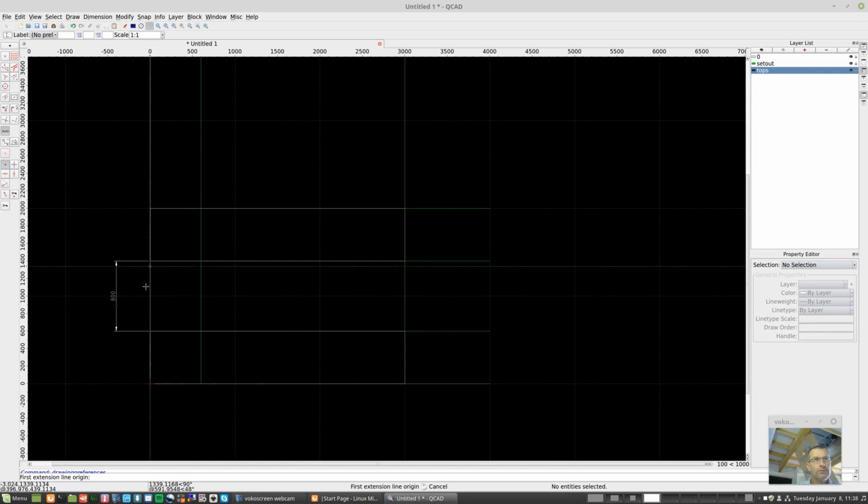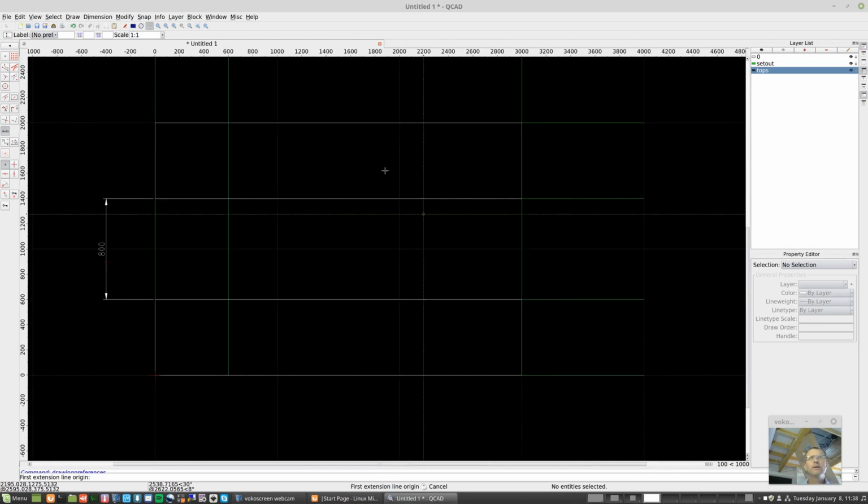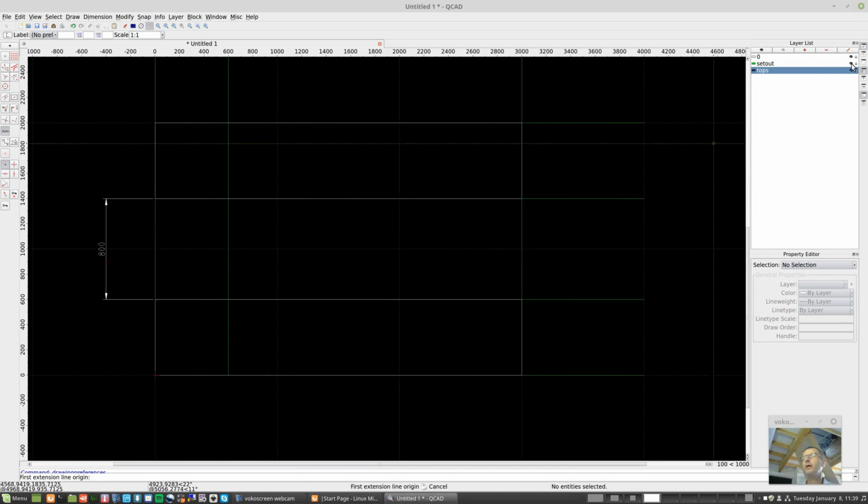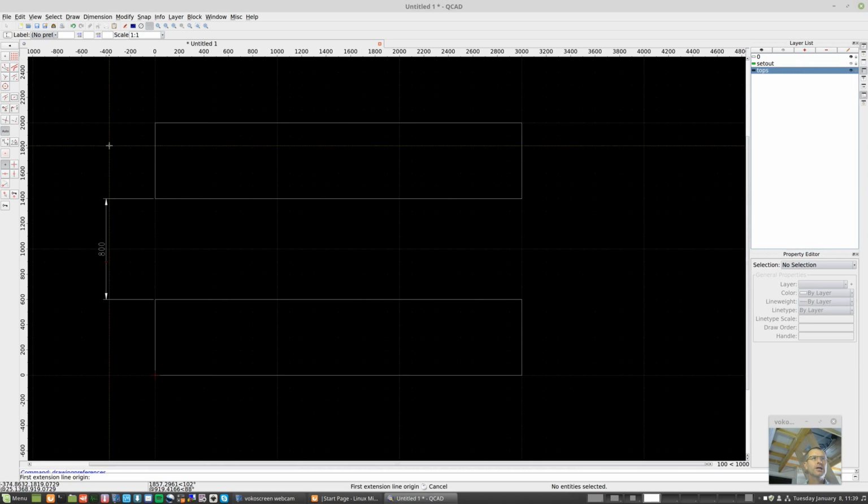So that would only leave 800 mil between. So having a return, which is quite a common option, would actually mean that these corners would be difficult to use. So with this width of 800, I would encourage you to not bother with corners at all, but keep this area clear. So I'll just turn off the set out layer. So you'd be able to use the full width of each bench top.